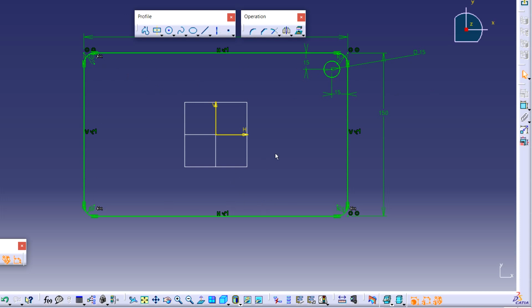So you can apply the mirror feature for that. So select that mirror feature and select this object. Next specify that axis. Okay, so that is the middle line. Okay, the next one, if you want to mirror these two items again downside, so again choose this mirror feature, and before that, first select these two items at a time by using Control.